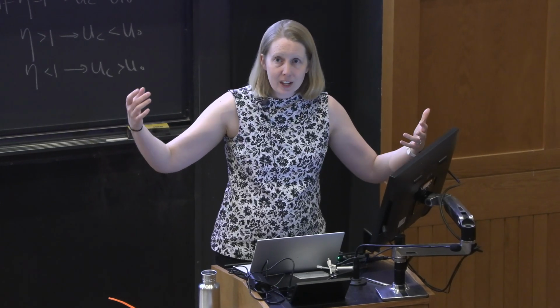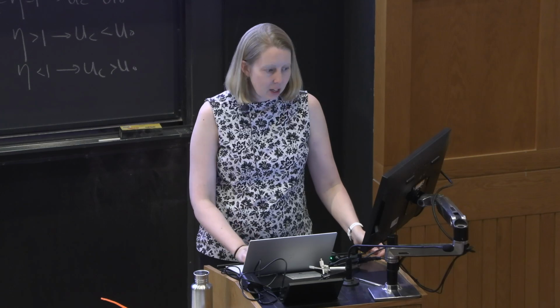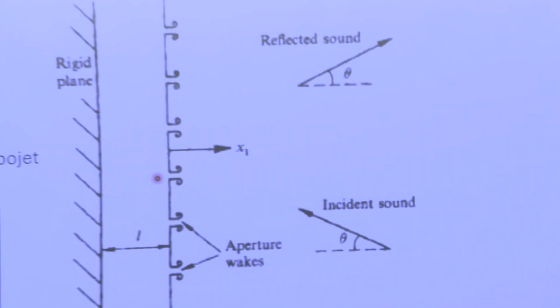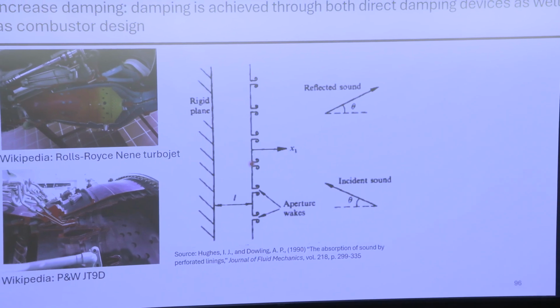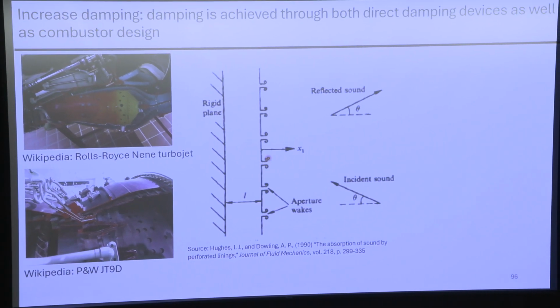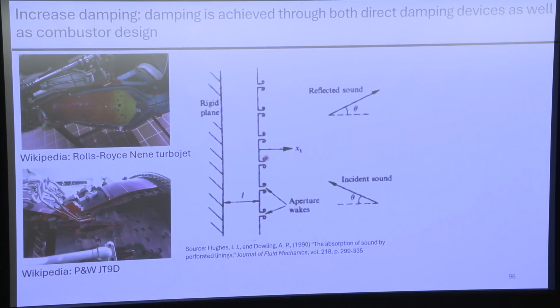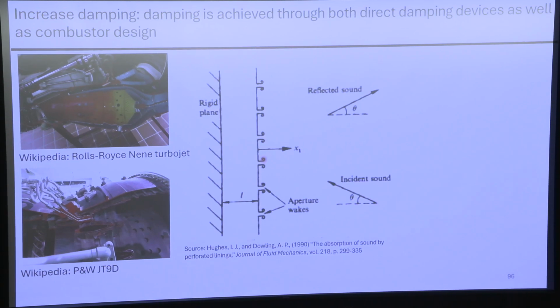At boundaries, however, they can linearly interact, and that's good for soundproofing, because when you force air through a tiny hole with a dilative, acoustic expansion, the separation off the edge of the tiny hole takes some of that acoustic dilative energy and turns it into rotational vortical energy. And so you dissipate some of that sound energy into vorticity. And vorticity doesn't make any sound because it's rotational, but non-dilative. So that's cool.